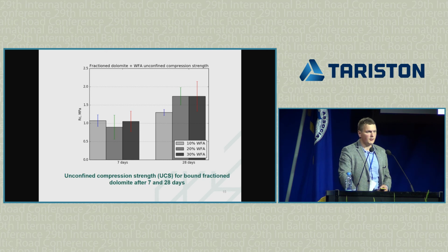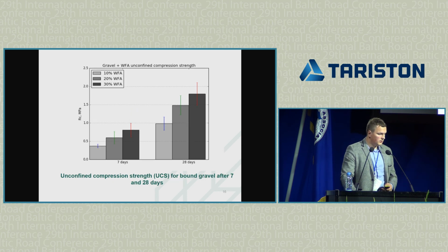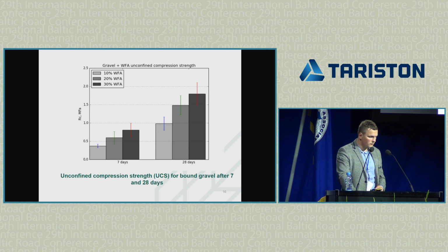So actually, increasing the amount of wood fly ash as a binder and keeping it longer in time, you can see that actually 20 and 30% are ahead. It can be seen even more clearly for the gravel, where increasing the amount of binder, we actually got higher unconfined compression strengths, both after 7 and 28 days.